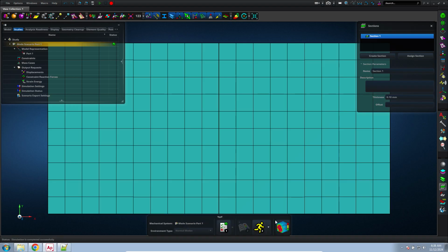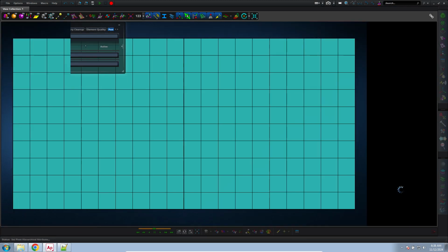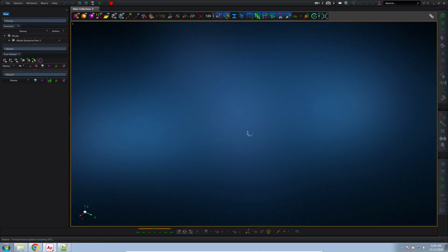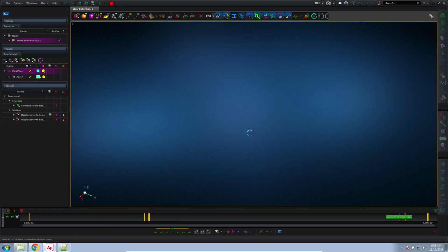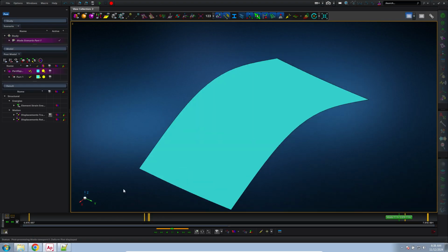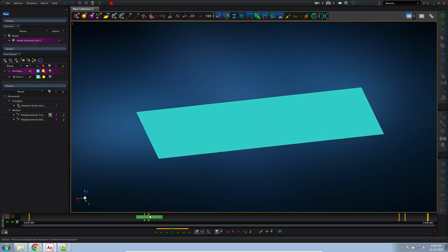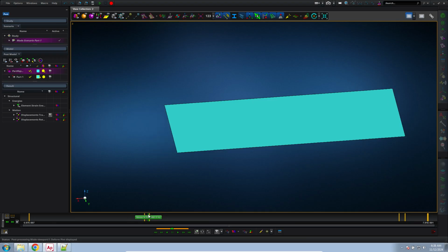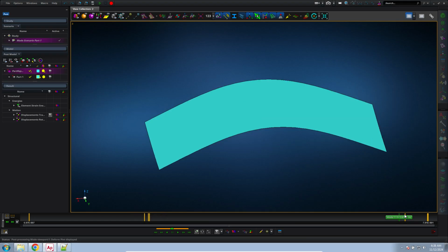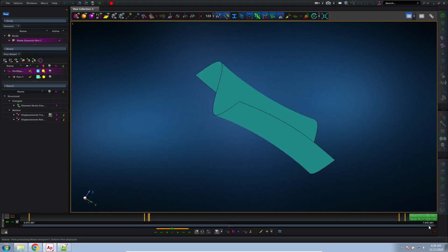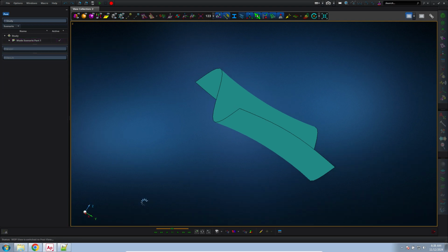one thing you want to make sure when you do a normal modes analysis is that the mode shapes look reasonable. So let's go ahead and take a look at the mode shapes. Okay, you can see that the mode shapes appear to be continuous. That's what you want. That's indication that the mesh is fully intact, if you will. Some of these look to be rigid body modes. Okay, that's a bending mode. Okay, this mesh looks good at the end, so let's go ahead and do this.